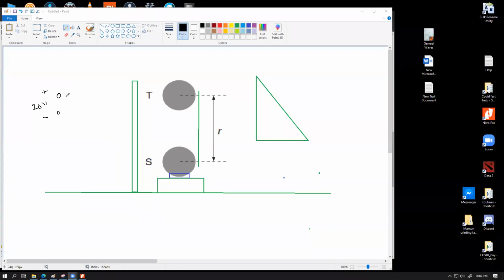The way, in my opinion, this circuit can work is that we'll definitely have a switch for functioning, and we can have a variable resistor. One of the sides will be connected to the ground. The other side will be our touching lead, and we can have a voltmeter. Actually, we can have a fixed resistor over here, and have the voltmeter connected across.